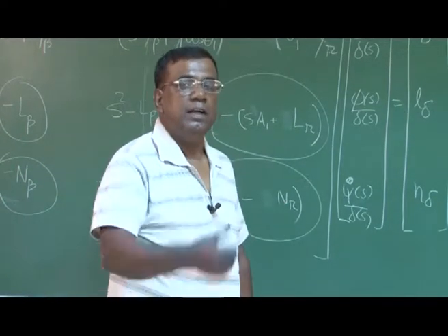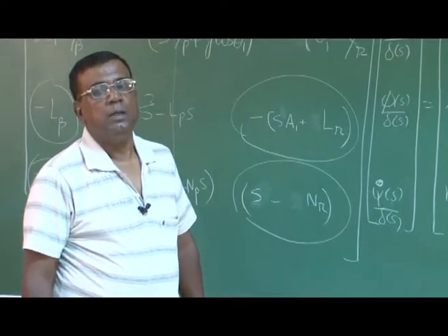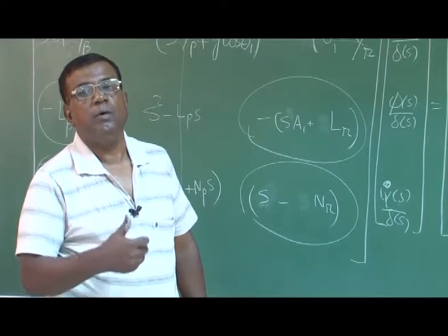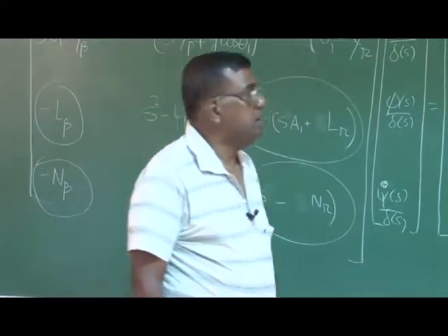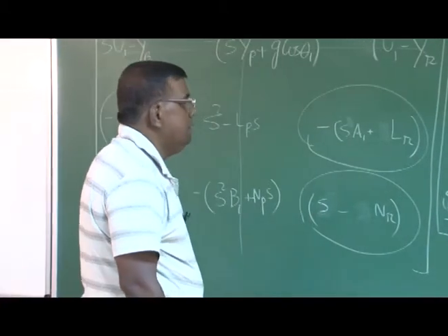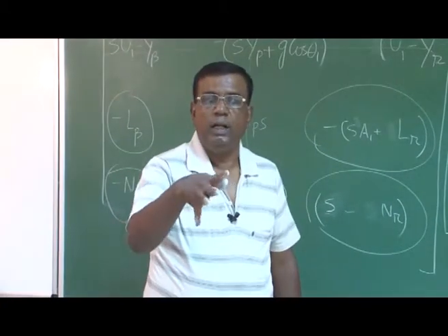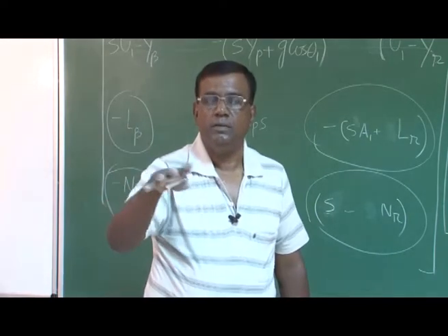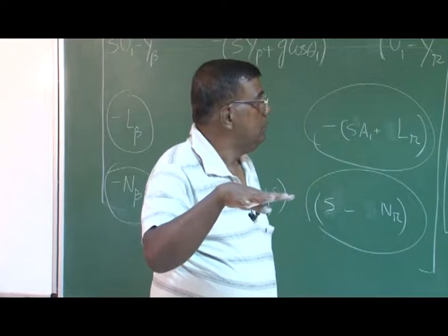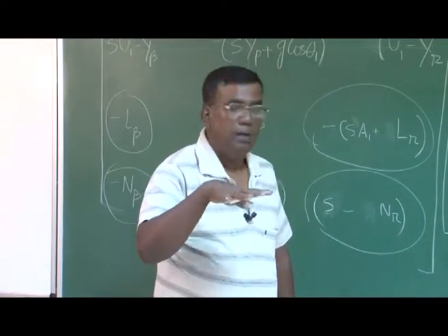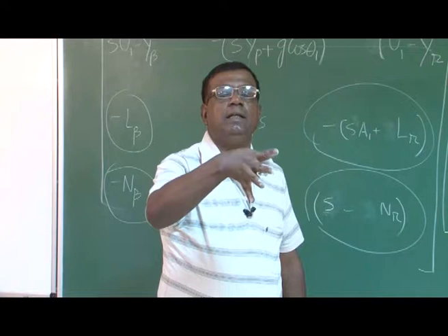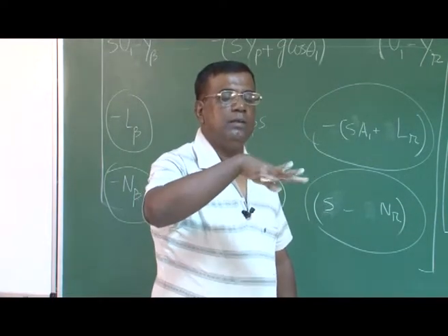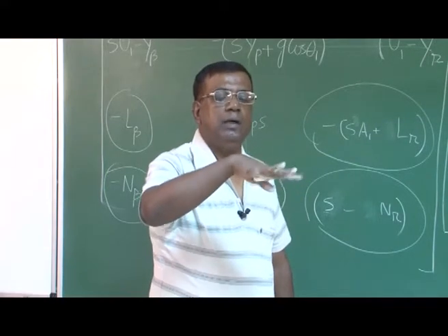That is, if I give a disturbance in the aileron, how is this aircraft going to respond to this rolling moment disturbance? The assumption here is, if it is rolling like this, it is not affecting any motion in the y direction, no beta is introduced, and no psi dot is introduced, only phi, one dimensional. It is equivalent of thinking in a tunnel, you are given a roll disturbance and it is trying to build or decay, whatever it is.